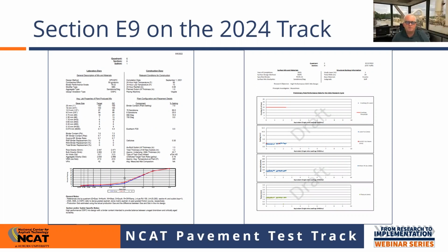And sandstone and slag is again, you want a mix that's going to provide good friction. So microtexture is important, and angularity, crush faces, microtexture. So sandstone and slag are great materials from that perspective, but they can tend to be absorptive and challenging to work with. You can get some breakdown in the plant, and Jim was kind of being kind.